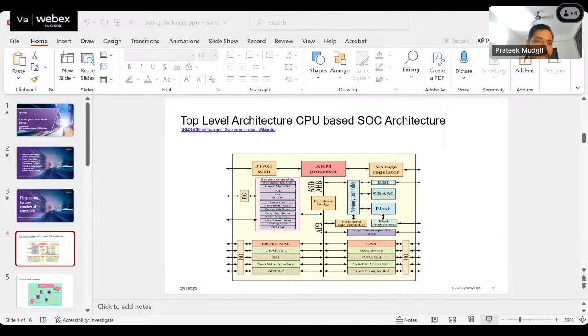So the problem comes when we are interacting with the external world through these ports, right? These are the ports which are talking with the external world. And the problem is that if I want to connect my JTAG with another JTAG in another IP, another SoC, we can't maintain a flop to flop path, right? We are not able to maintain the flop to flop path, because we don't know the trace length.